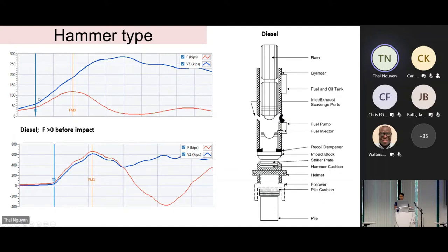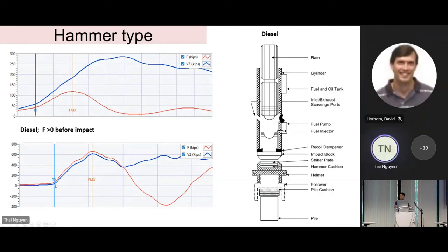For both of these graphs, the pre-ignition force is about 40 kPa. So 40 kPa here, and down here is also about 40 kPa. But when it's soft driving, that portion is pretty high compared to the maximum. In the soft drive, that 40 kPa is about 1/3 of the peak, whereas this is almost nothing, almost zero.